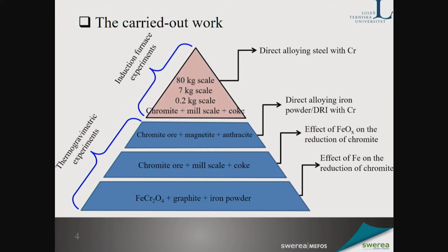And in another group of experiments, I also carried out some induction furnace experiments to check the possibility to directly alloy steels with chromium in, for example, the induction furnace. The experiments were slightly upscaled from 200 grams to 7 kilos and up to 80 kilos.